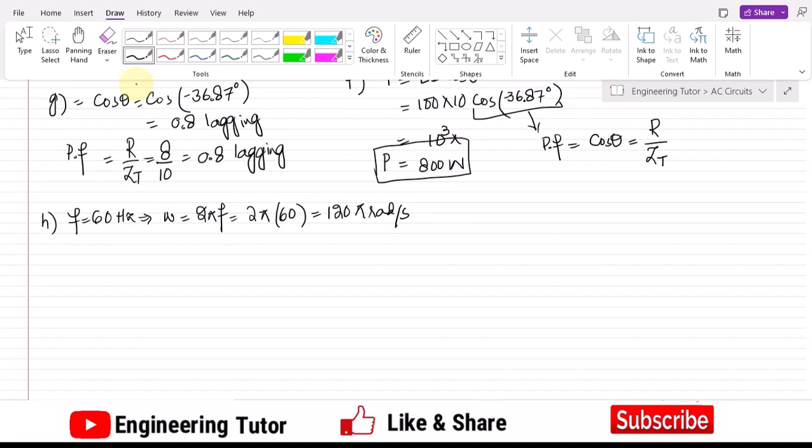In order to find the value of the total voltage here, the total voltage was 100 at 0 degrees, where this voltage is basically the RMS value while this is the phase angle. So in order to write them in the form of the sinusoidal wave, I should have the peak values. So converting the RMS value into the peak value, I have to multiply with the square root of 2 and that is the RMS value it has, and after it the sine of omega t plus theta.